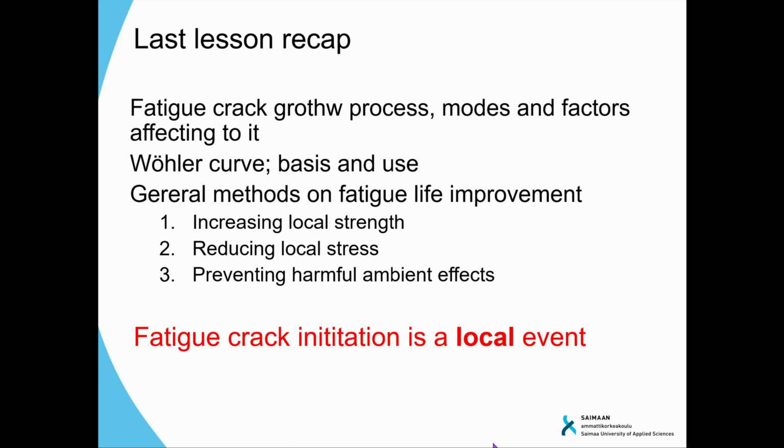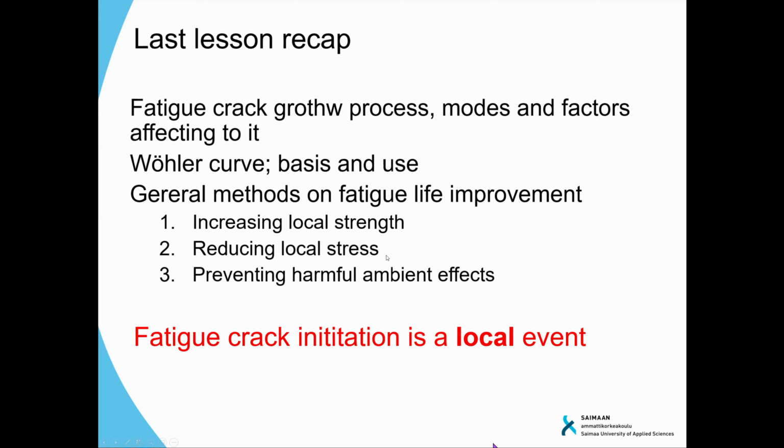And in all these actions which can be done below these, the practical actions, you should remember that the fatigue crack initiation is always a local event. So the local area where the crack wants to be initiating and wants to grow is the area you need to affect. You don't necessarily need to affect large areas. It could be only very small area and you can still gain benefit out of it.